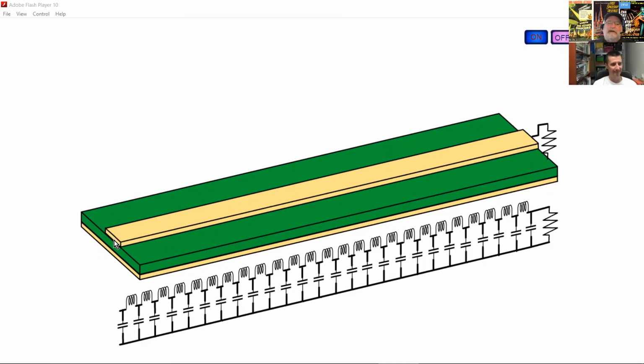When I have an electric field, it generates a voltage between the two conductors. So if I put an electric field between the first conductor and the second conductor, I have a voltage difference between them. If it's static, not changing, there's no current flowing between the signal and the return. But if that electric field changes, if it increases, for example, wherever I have electric field lines, I'm going to have a new kind of current, and he called that displacement current. It is just as real as the motion of charges flowing through the conductor.